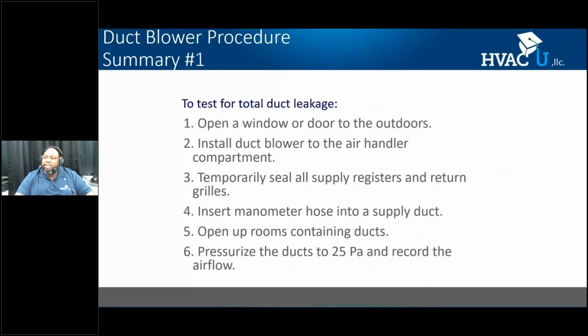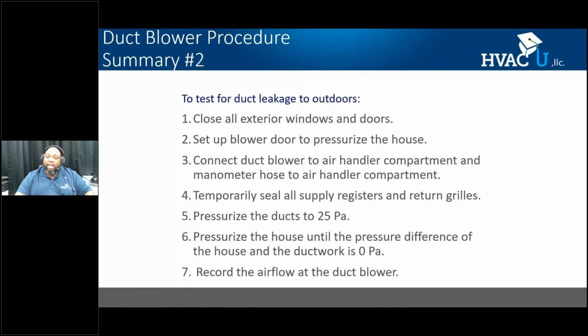All right. When we test leakage to outdoors, you're doing a similar test. However, you're going to be running it with the use of a blower door. So in this procedure, you're going to close all exterior windows and doors. You're going to set up a blower door to pressurize the house. Now, that's a distinct difference from a normal test. Normal industry standard is to depressurize. In this case, we're going to pressurize this house and turn the fan of the blower door actually the opposite way.